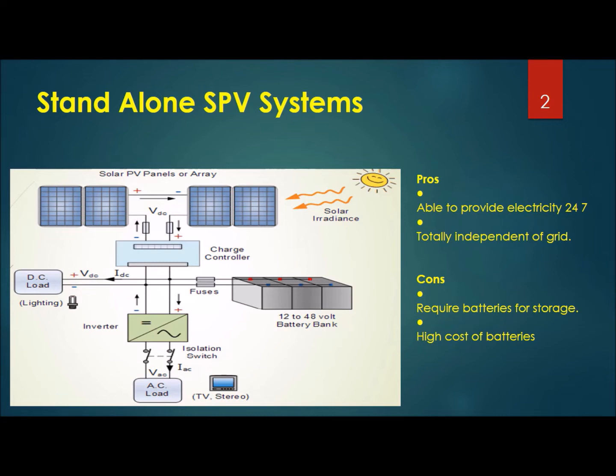Therefore, to form a DC bus of around 360 to 400 volt, several photovoltaic modules are to be connected in series to form a PV string. However, with such an arrangement, the system exhibits multiple local maximum power points under non-uniform solar irradiation levels.